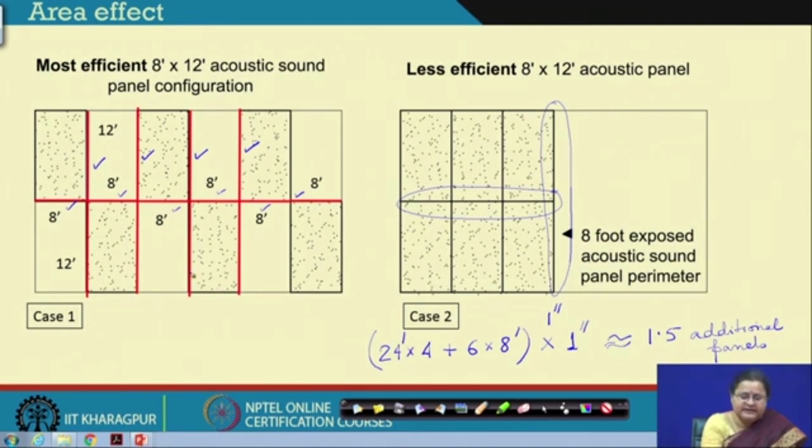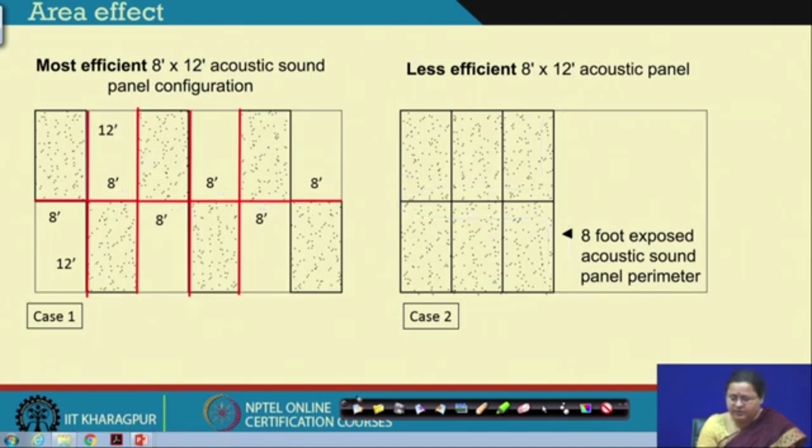As well, these are coming down at an interval of 1 inch, which creates a diffusing effect of the sound, which adds to the quality. So, we need to spread the absorbers as much as possible if the area permits, and we can get more effective absorption with a better quality.